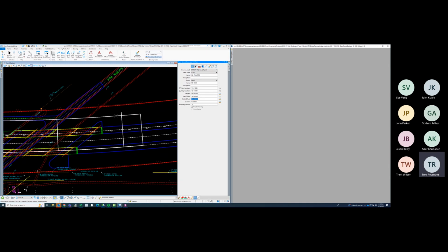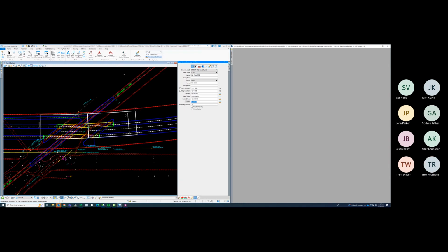They were usually called sheet clips or something along those lines previously. This left and right offset can be changed also. So if I change it to 80, then this line, I guess all this offset means is the offset from your baseline that you chose. So if I go to 120, then it's going to be way out here. And the same thing for the right side. So in this case, I'm just going to use 100. You can change it to whatever you want it to be.